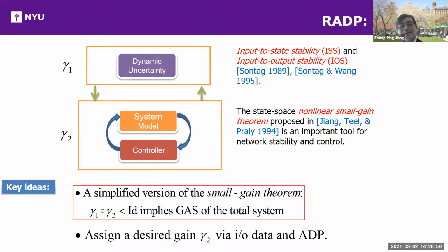Here there's a tool which you can use to prove robustness for interconnected systems. There's an interconnection between the dynamic uncertainty and the model. So this is the instability mechanism. Interaction is not good, even though both systems can be assumed stable. But when they start to talk together, you can generate an unstable network. This is an interesting phenomenon observed by a lot of people, in power systems, in industrial processes, in any network of robotic systems. So you need to introduce additional conditions to guarantee that interaction among system components will not destroy total network stability.